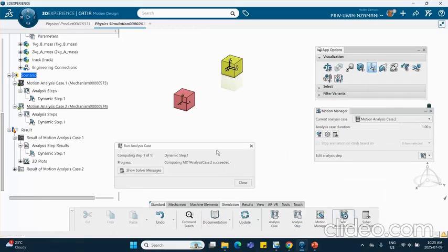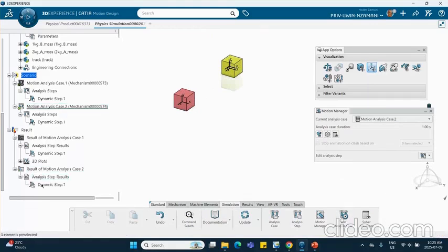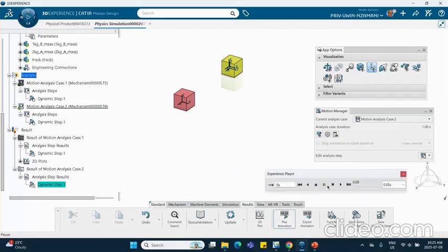Okay, very good. Select the results there. Go to results, animate. You see that? That's not the way it's supposed to behave. And it is unfortunate, however, because this happens because the markers are at those corners. Why don't we go and create the markers right at the centroid of these blocks?